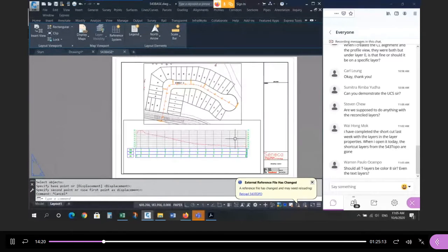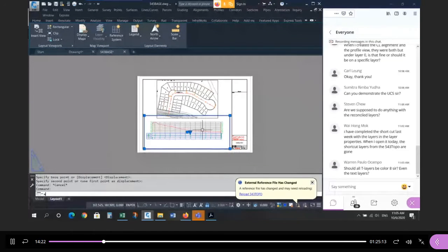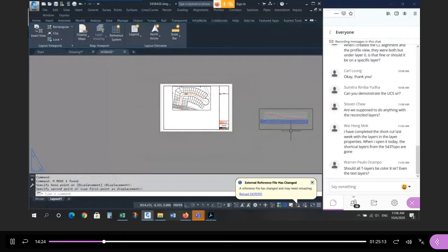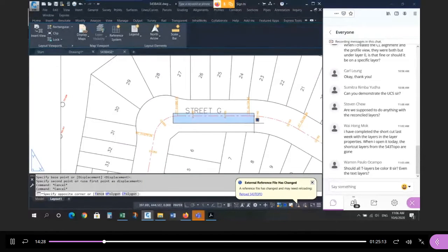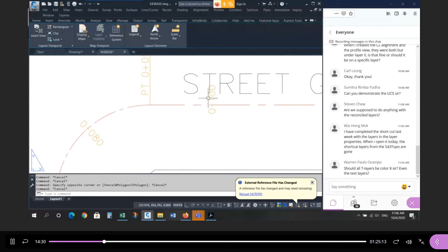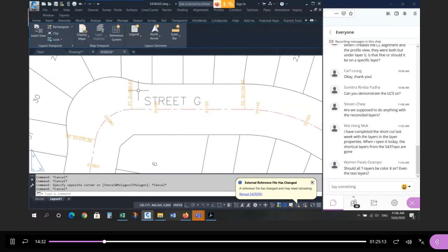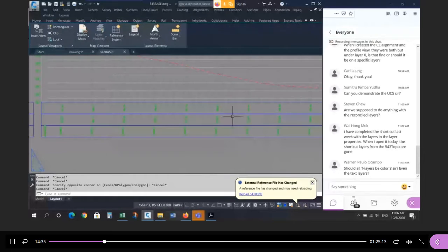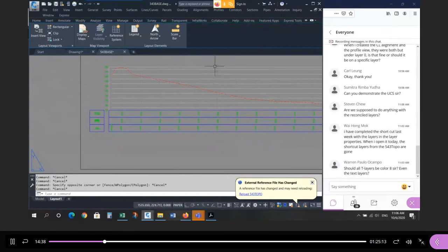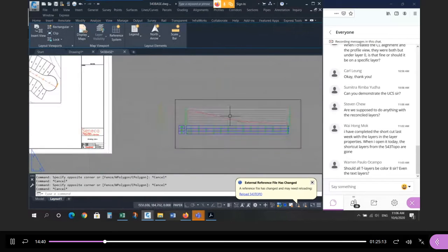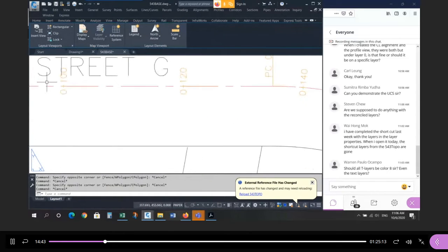The last thing you want to do is line up the profile so that the stations, this piece from here to here, is horizontal to the view. So station 100 here in the plan should be directly above station 100 in the profile, right? Station 100. So you want this vertical gray line here, this vertical gray line, to be directly below station 100.